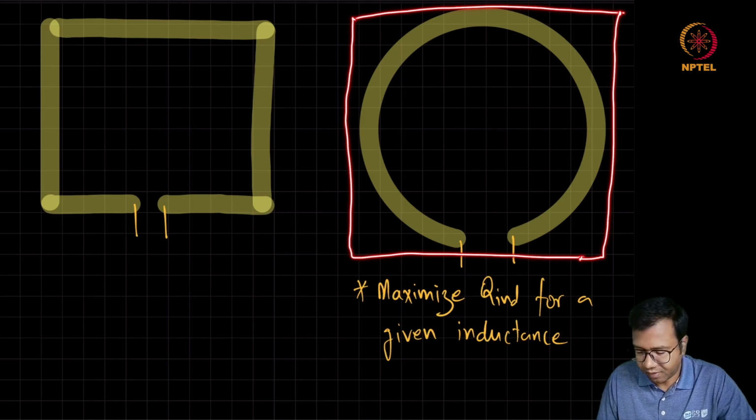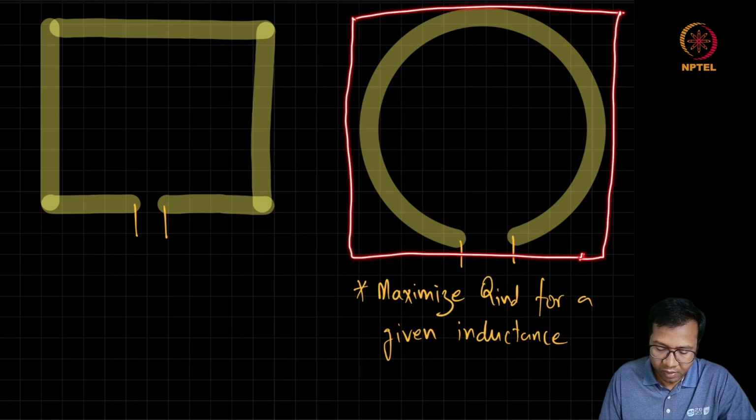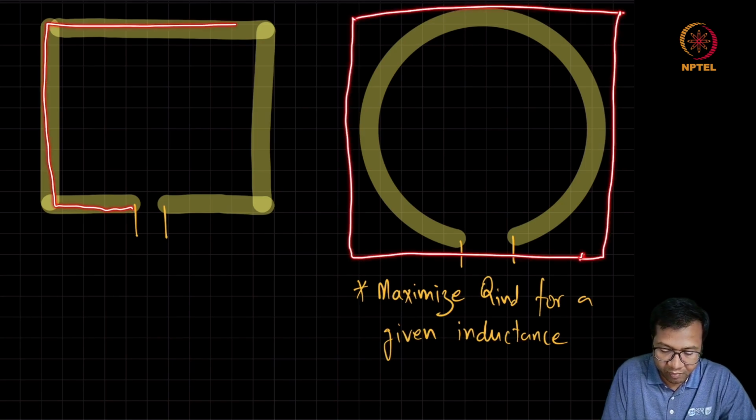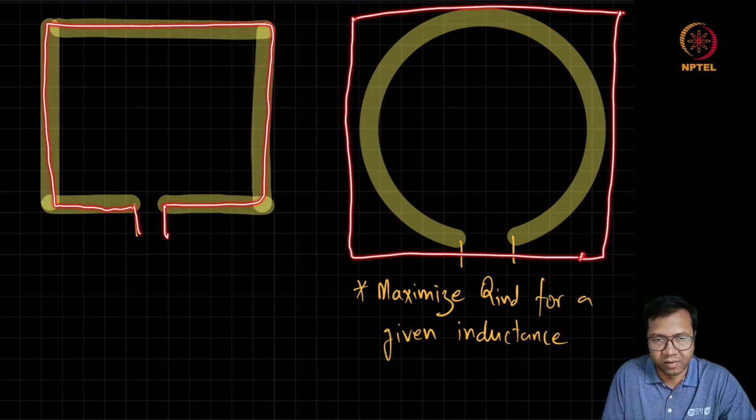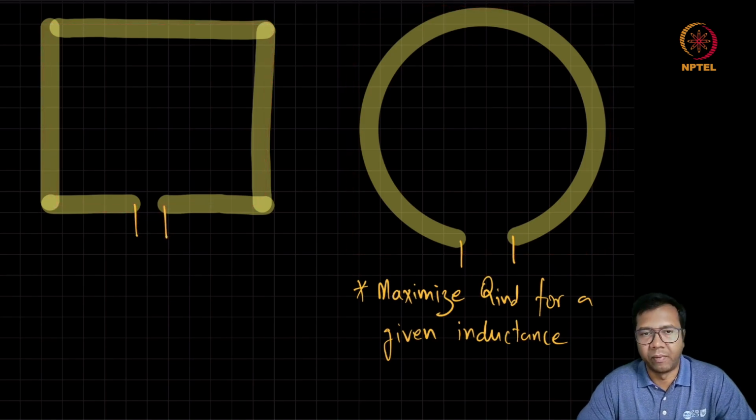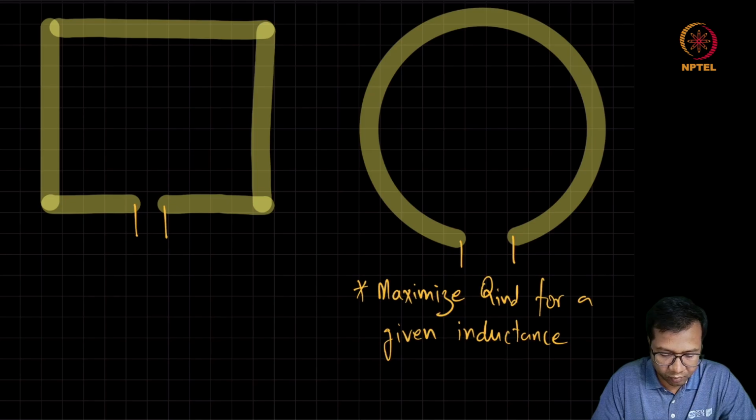So within this enclosed square type of enclosure, if you want to maximize the inductance value, not the quality factor, just the pure inductance value, it will depend on how we can maximize the A inner in the given bounding box. And for such a scenario, a square shape will give the maximum inductance in a given square type of bounding box.